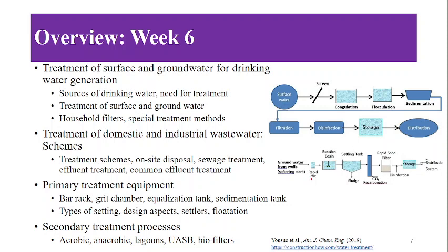The groundwater treatment includes the rapid mixing, followed by the reaction basin, where coagulants or flocculants are added. Next, the settling tank, in which sedimentation occurs, and recarbonation, so that carbonates are present in the water, which are vital for drinking water. And next, the rapid sand filter for removal of fines, and then the storage, and then to the distribution systems.